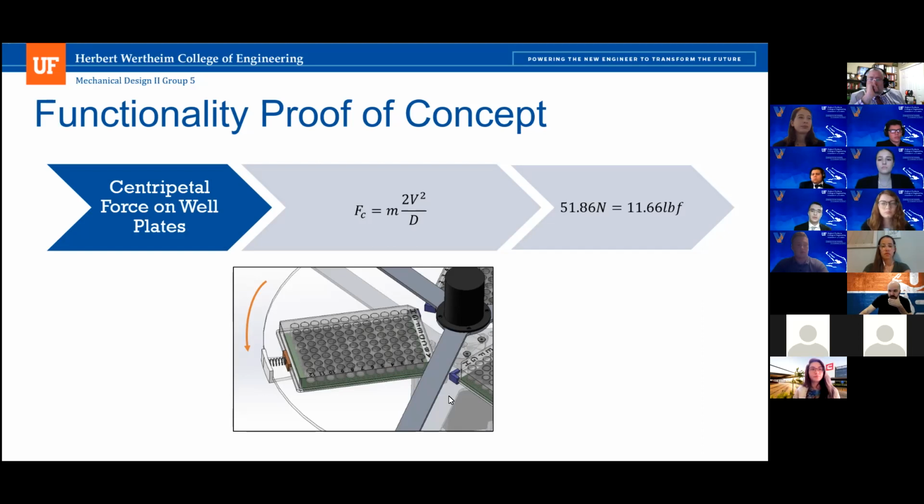Now, I believe the reason we didn't opt for a recessed or a more rigid container is that although these are standard ANSI well plates, there is some variation in the dimensions. So we decided that a radial spring would be the best way to accommodate these variations of a few millimeters, ranging from 4, 5, 6 millimeters in variation, depending on how the bottom lip of the well plate is shaped. But no, that's a great question. Something we should look into.